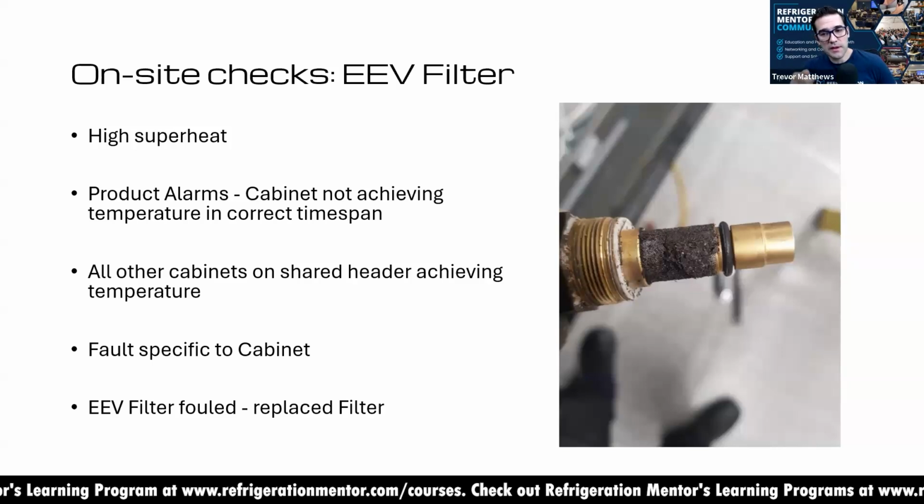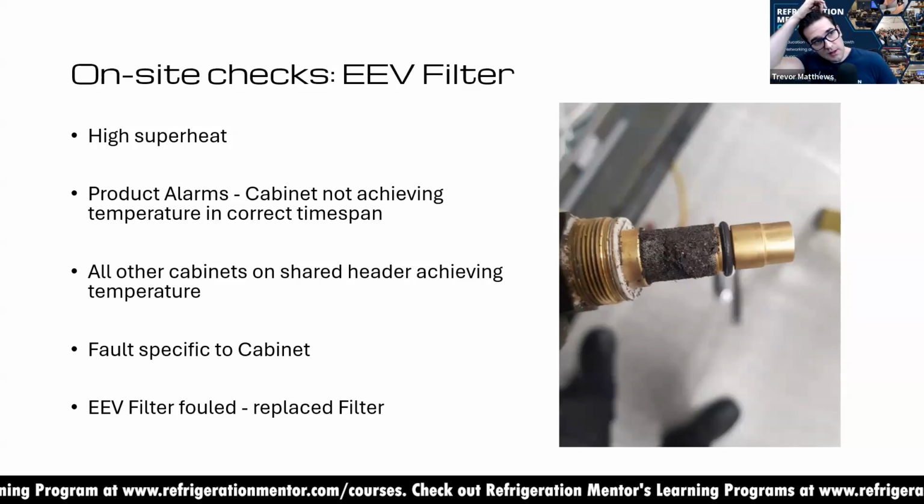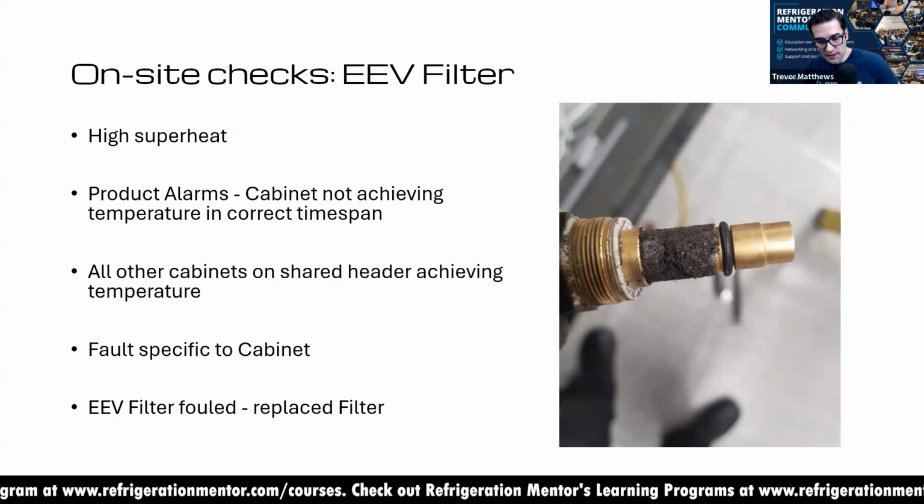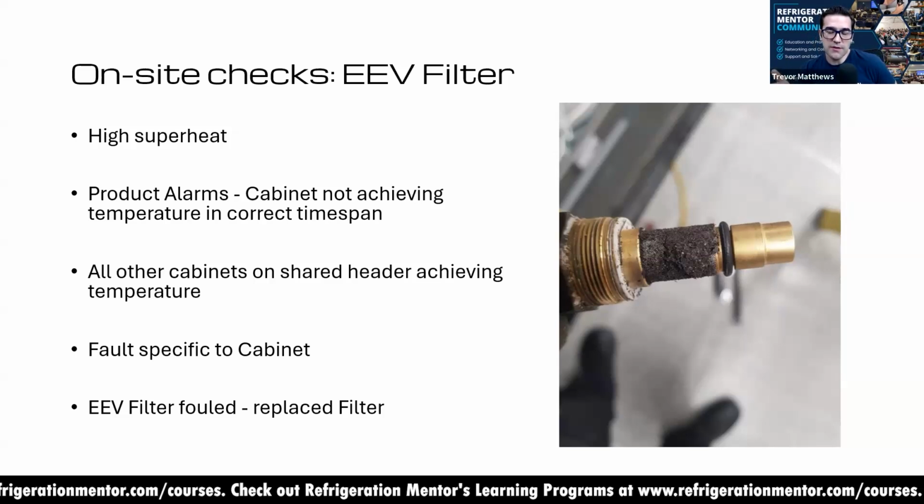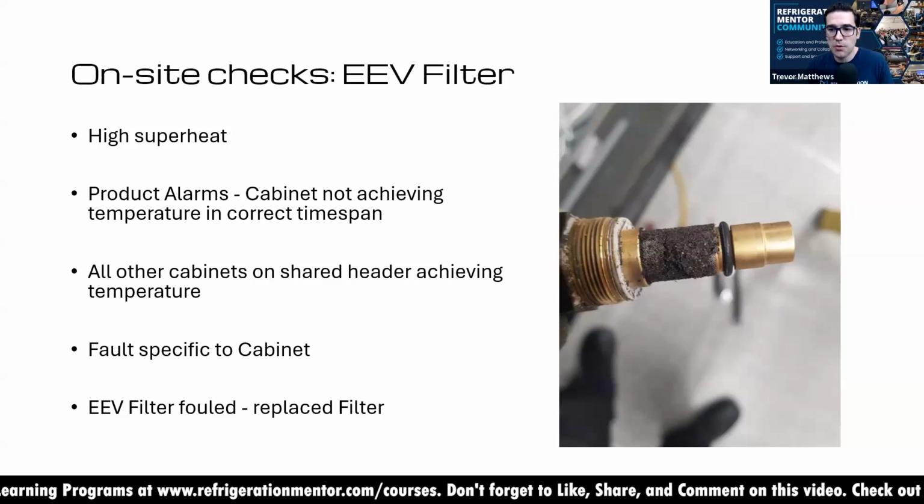And this is another thing that I just learned from a technician in one of my CO2 courses. Right now in the UK, you can blow out the CO2. You pump the circuit down, say you have 12 bar left in a low temp circuit, or 200 psi, because that's vapor left. Right now you can still blow out all that CO2 to the atmosphere. It's not against the law anywhere in the world, I don't think, at this point, or there's not much regulation, but we can release natural refrigerants.